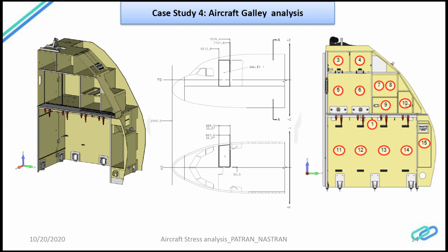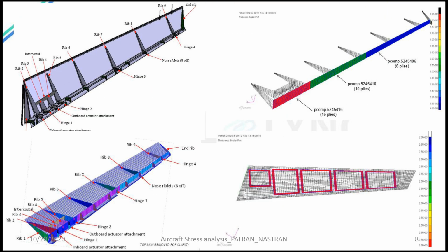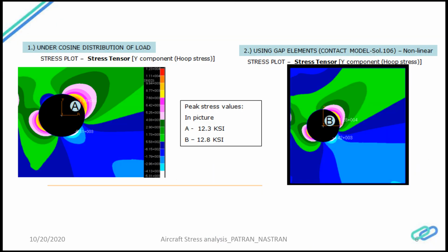If it is a high load, then the way you can pass is to come up with a local stiffening on the panels which are experiencing very high stress, and then mitigate the problem using hand calculation. You can justify the metallic fittings using hand calculations and the rest of the structure using finite element analysis, or it might be a combination of both hand calculations and finite element.